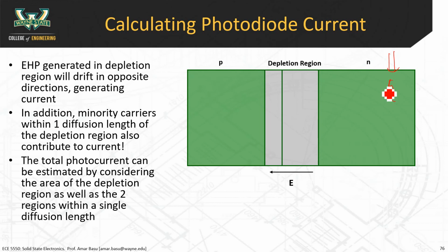Do you remember how they diffuse out in both directions? If you have a specific region where you're generating a lot of carriers, in that region you have a high excess carrier concentration, and outside it you have less excess carrier concentration. So diffusion happens from high to low concentration. So the holes and electrons just diffuse away from the illuminated source. But notice that the holes and electrons are both diffusing outwards away, right?